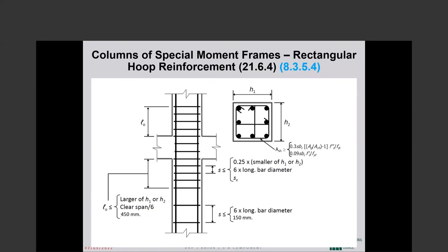And when we end up with 1.5 inches or 1 inch spacing, concrete cannot be placed anymore. So that is a hidden limit on the strength of concrete that we can use in columns in high seismic areas. Yes, ACI does not have a formal upper limit on the strength of normal weight concrete, but here there is a hidden limit. Okay? The only way to get around this is if, as f'c increases, we can also increase fyt, the yield strength of the transverse reinforcement.